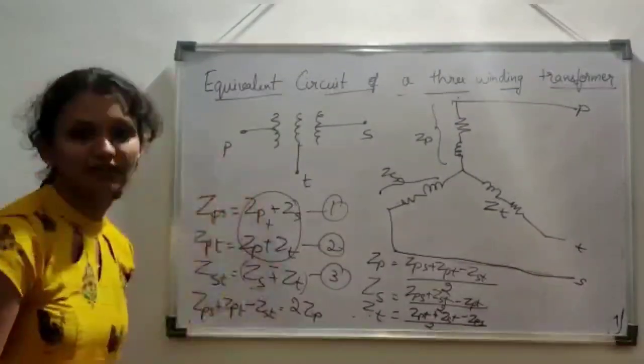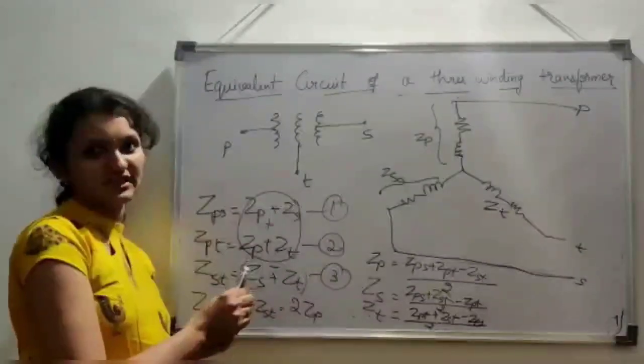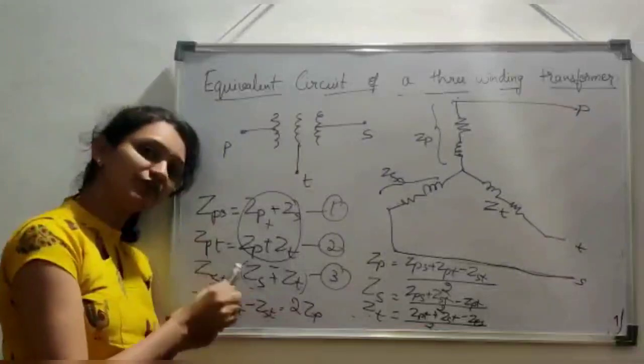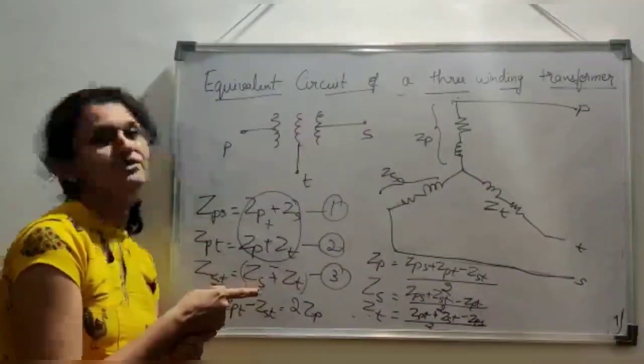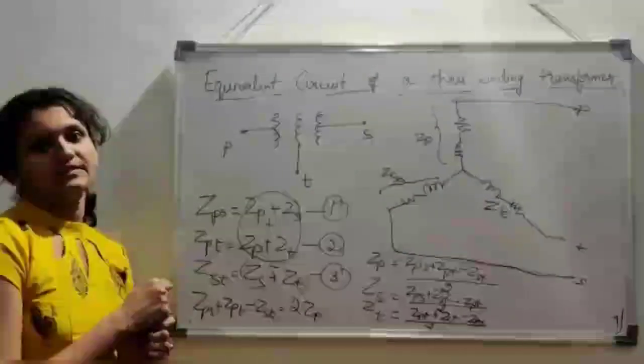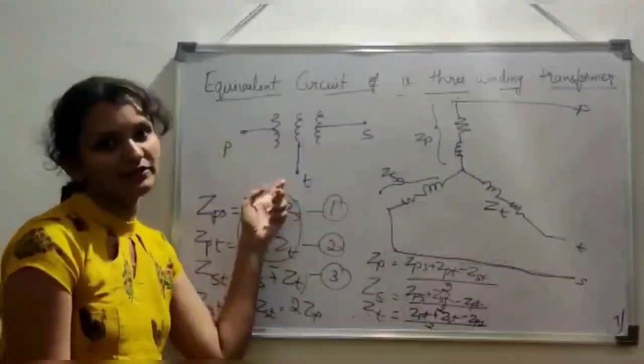Okay, the advantages of the 3-winding transformer are, these are used for interconnecting 3 transmission lines, each working at different voltage and power levels. They find extensive utilization in high voltage laboratories. Static condensers may be connected to the tertiary for reactive power injection.